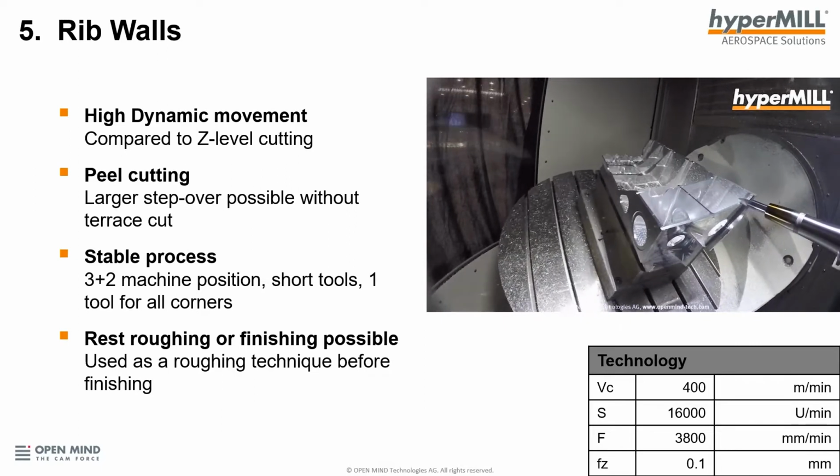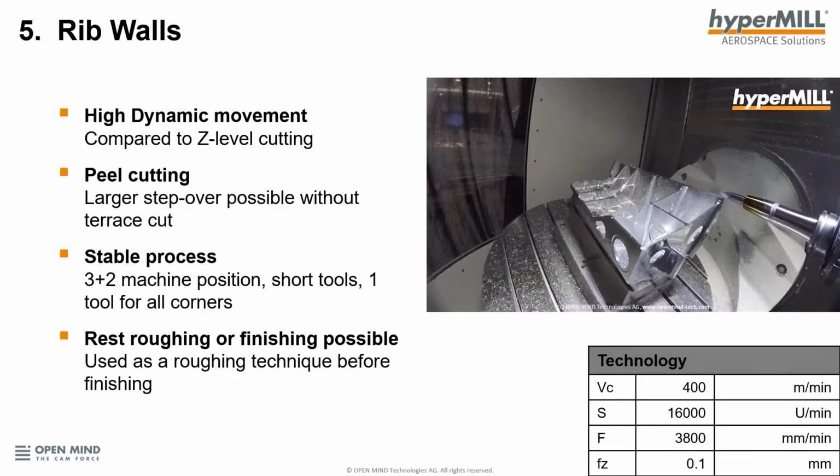And the nice thing is the different orientations that you have between those different ribs. Because of the big radius of the tool, the blending between them is a great result. It does hide maybe some inaccuracies that you might have on your machine tool, because this radius diameter is hiding that a little bit. So the blending as you go between different orientations and different faces, if you really look at it in detail, is perfect. It's a really nice process.